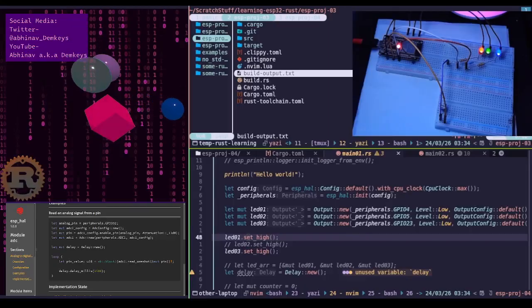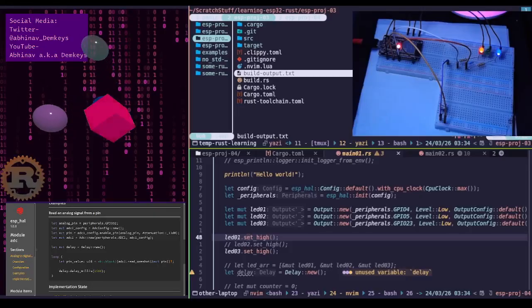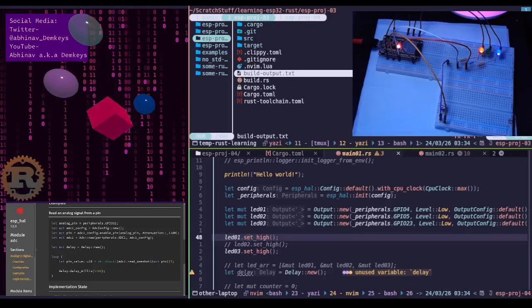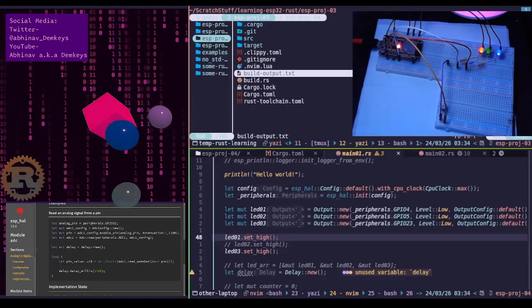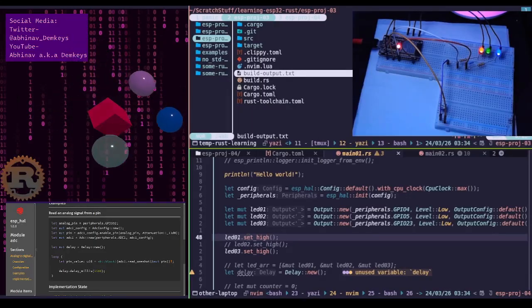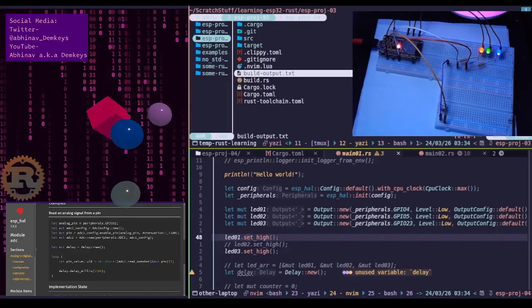Okay, how your ESP32 sees it. When you connect pin 1 to 3.3 volts, pin 3 to ground, and pin 2 to GPIO4, when the potentiometer is turned all the way left, pin 2 is touching the side connected to ground, and your ESP32 reads 0. When it's turned all the way right, pin 2 is touching the side connected to 3.3 volts, and your ESP32 reads 3.3 volts. In the middle, you get roughly 1.65 volts.